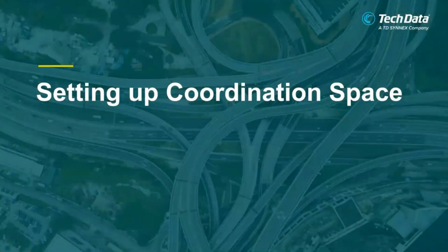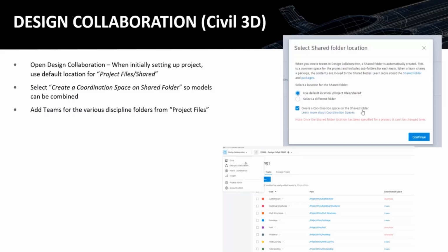Okay. And once you already know how to push your current file into the cloud, you need to know how to set up the coordination space as well, because this coordination space is for you to monitor your clash analysis.